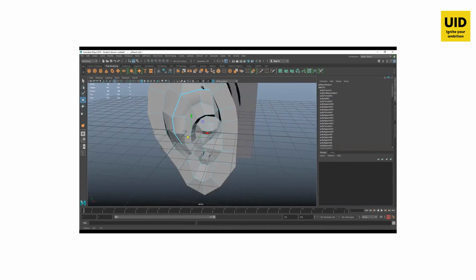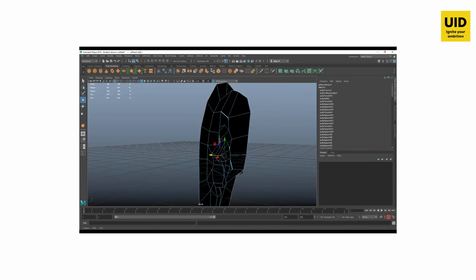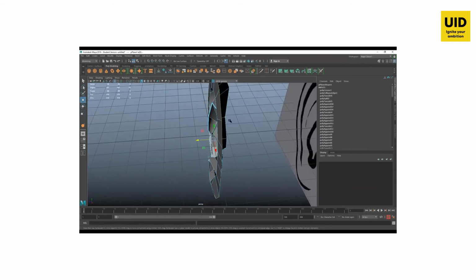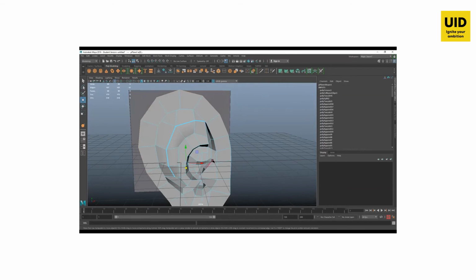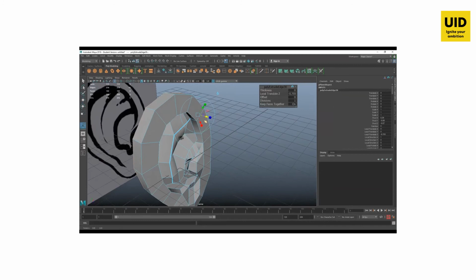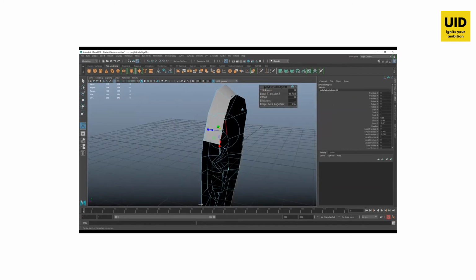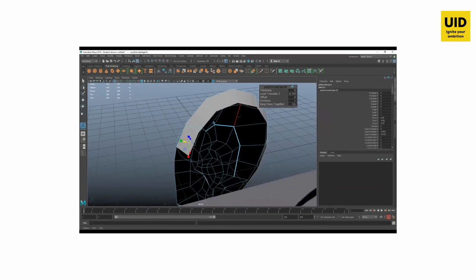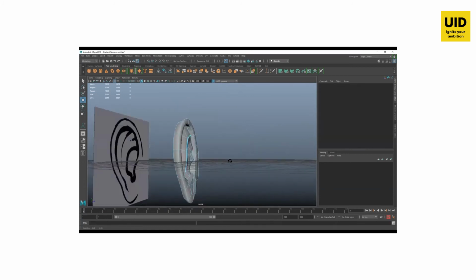Next, let's just create the boundary and just select them. I'll deselect these because if you fill the ear, it gets connected with the cheekbone here. Okay. And after this, it bends like this and goes to the back. So I will not select this much area because this can get connected to our cheekbone. Control E, move it back, okay, and also in the Y direction, so that we have bending in this way, okay. Be careful here if they penetrate each other like this; then push the inner one back and down a bit so that there is no merging like this. Press 3, good.